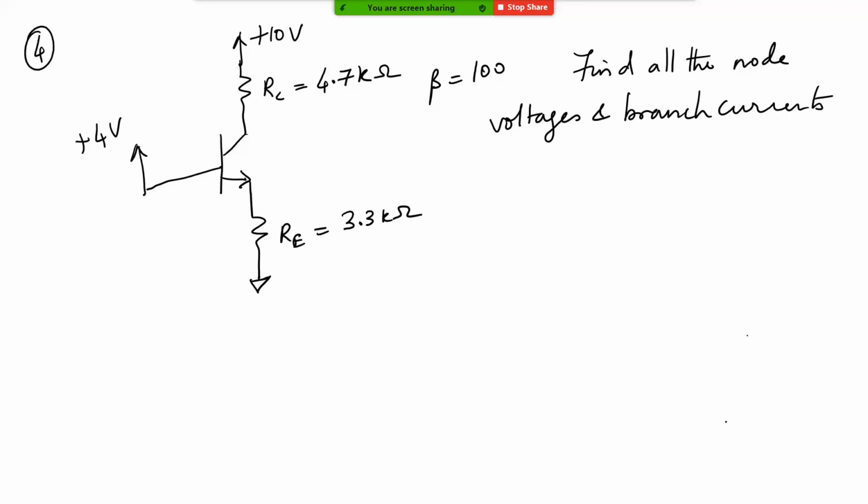Okay, so here there is a trick. Sometimes, there is one thing that I want you to understand. In some problems, when you are given the value of IC, VBE for a certain value of IC, then you can calculate the exact value of VBE for the current that is flowing. But what I have given now is more typical about how you would be not only analyzing circuits but also designing circuits.